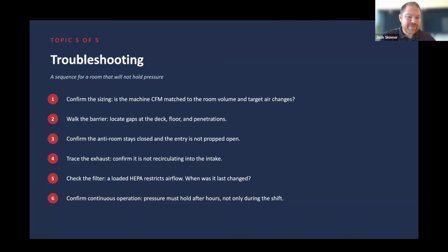First off, if you weren't getting it from the first place, you probably never had enough CFM and enough negative pressure, or your containments weren't set up right. Kind of simply, when someone calls, I use a couple simple things. I say the door, check the machine. And by the machine, I'm saying, is the filter overflowed? Is it even turned on? Did it trip off like you talked about? Check the containment, make sure all the walls are sealed. Check the building system, so the intake, the exit, the air conditioning, and then check the monitor.